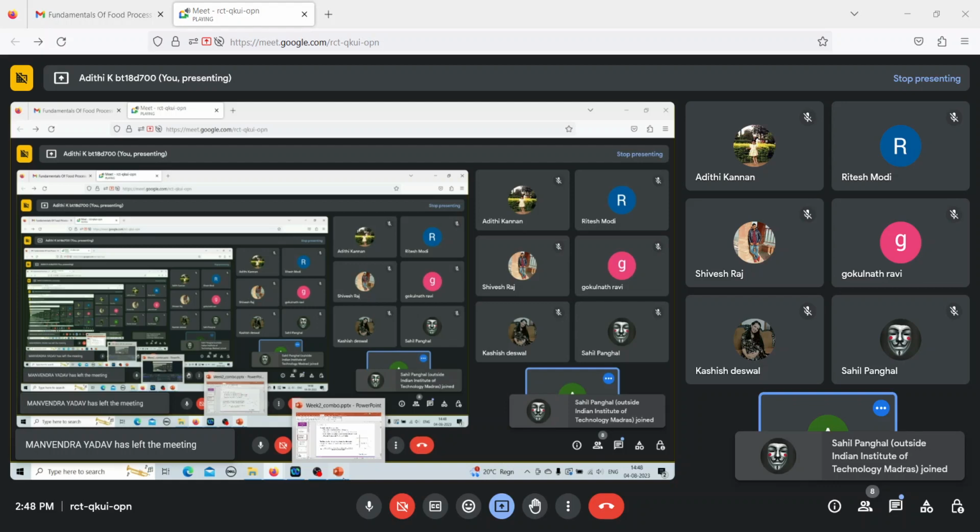Basically the concept is you are giving something sinusoidal in nature. So in a dynamic test, the material is subjected to sinusoidal stress or strain, and the strain or stress response is measured. If you are giving stress, measure the strain. If you are giving strain, measure the stress. In either case, it is of a sinusoidal nature.